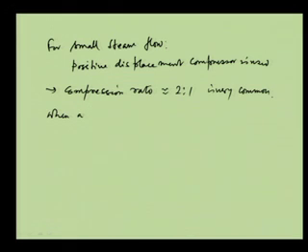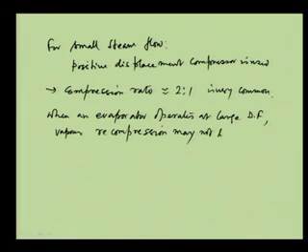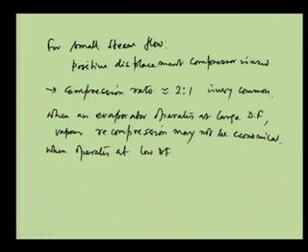When an evaporator operates at large driving force, vapor recompression may not be economical. At the same time, when it operates at low driving force, a large area is needed.